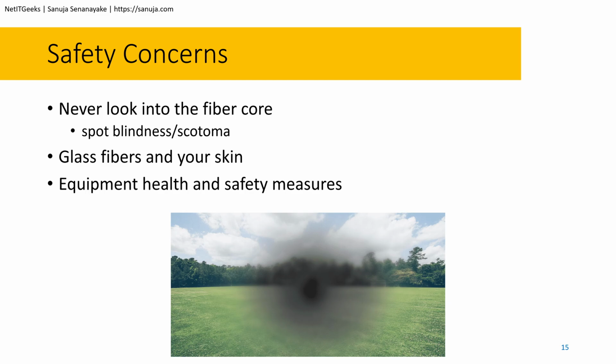So this is a really important slide, even though it doesn't have much information, because I'm going to quickly give you the most important things that you need to remember when working with fiber. You should never ever look into the fiber core when you work with fiber optic cables. It doesn't matter if your manager, your supervisor, your team leader, or your senior people tell you that the cable is disconnected.